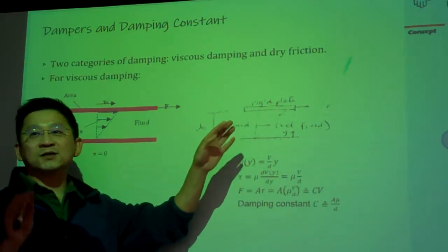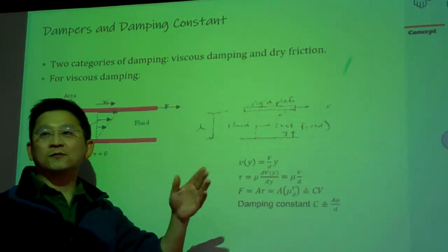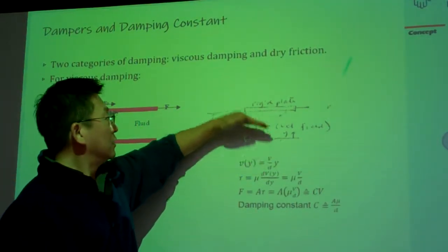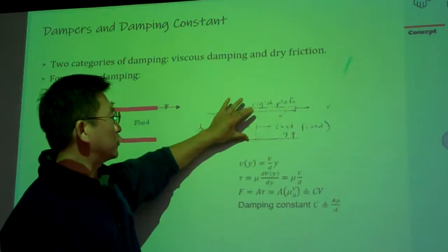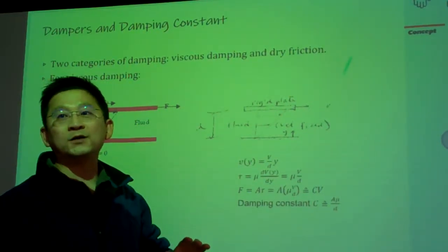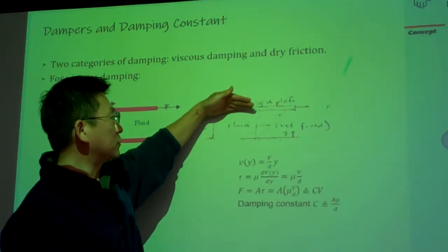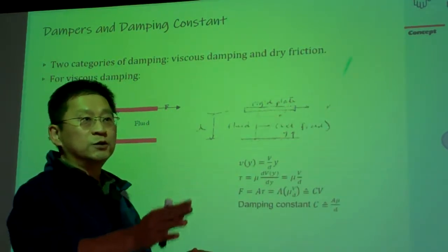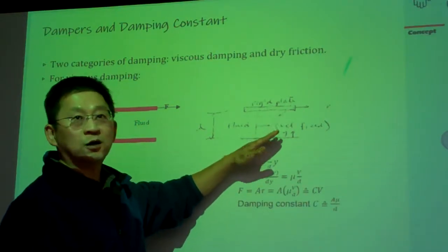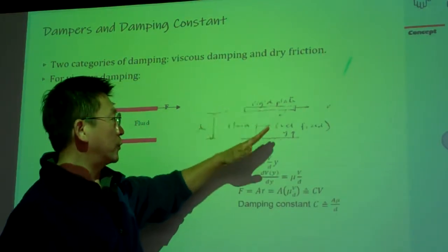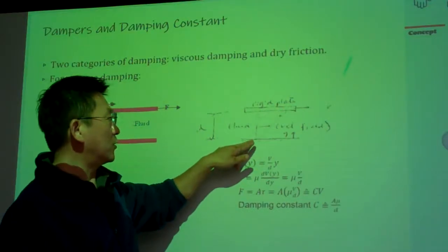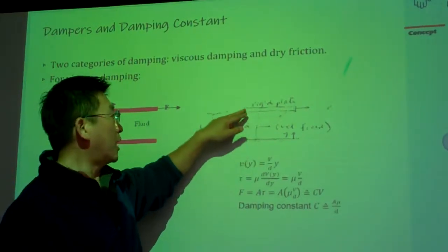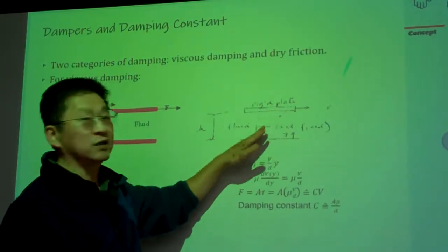That is called the shear stress in the fluid, right? So everything is linear. The bottom one is fixed. The top one is a plate in between that is filled up with certain viscous fluid. And the setting is such that the plate on the top is dragged, and when reaching the steady state, the distribution of the velocity within the fluid basically is in linear fashion. Zero at the bottom where the substrate is motionless, and maximum at the top, everything is linear.